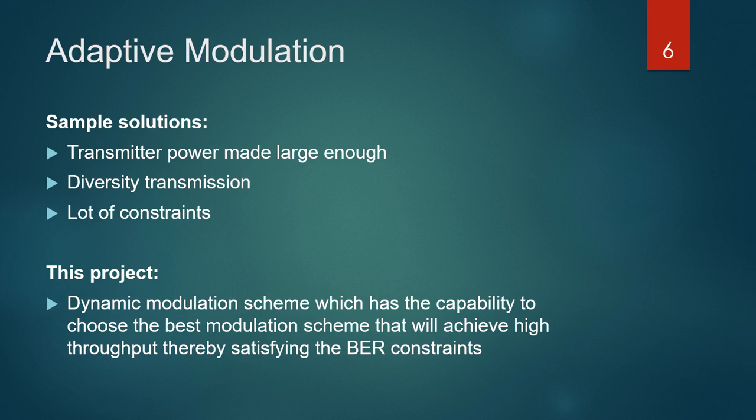Thus, for high data rates to be achieved, robust and spectrally efficient methods of modulation and coding are required in order to combat the effects of flat fading channels. In a situation of a reciprocal channel, if the channel characteristics can be estimated by the receiver and the receiver sends some pilot signals to the transmitter, then the transmitter can in advance be aware of the channel and can adapt its transmission methods accordingly. This method, which is tailored specifically to the channel at that point of time, will give higher data rates.